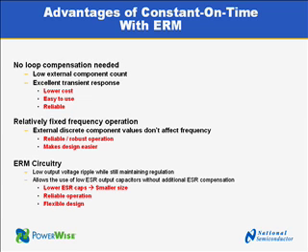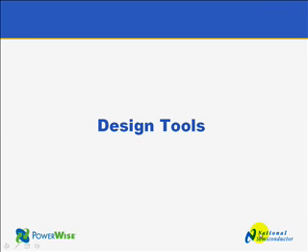The emulated ripple mode circuitry gives you a low output voltage ripple while still maintaining regulation. It allows the use of low ESR output capacitors without additional ESR compensation. Lower ESR caps means smaller size, reliable operation, and flexible design.